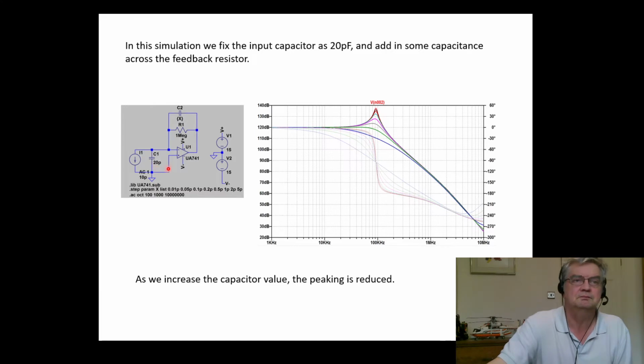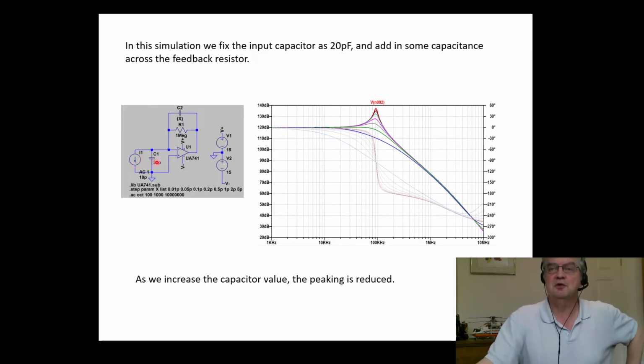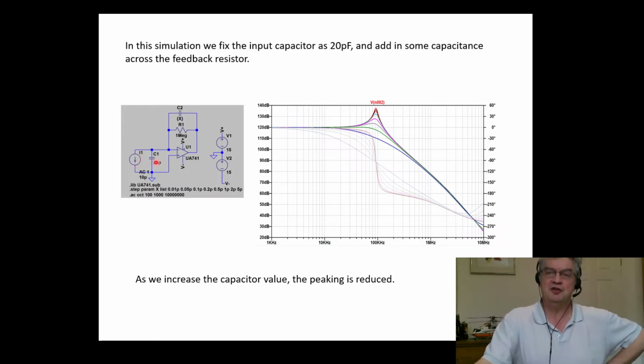Which is great. And that's good, because in these sources, or current sources, particularly photodiode ones, there's a little capacitance built into the junction, and that capacitance has to charge and discharge normally. So if you can actually short it out with the measuring system, then that allows you to extend the bandwidth, because anything involving capacitance introduces delays, and anything introducing delays introduces bandwidth limitations.